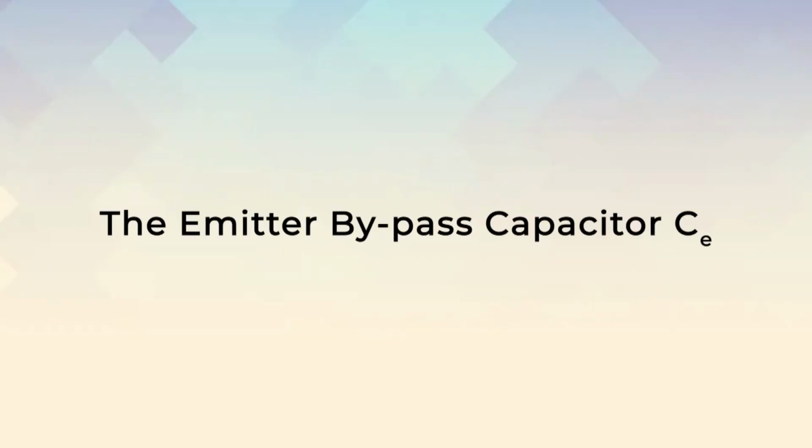Now, the role of capacitance in the amplifier. Other than the coupling purpose, there are other purposes for which a few capacitors are especially employed in amplifiers. Now, to understand this, let us know about the role of capacitors in amplifiers. First one is the input capacitor C in. The input capacitor present at the initial stage of the amplifier couples AC signals to the base of the transistor. Hence, the input capacitor allows the AC signal from the source to flow into the input circuit without affecting the bias condition.